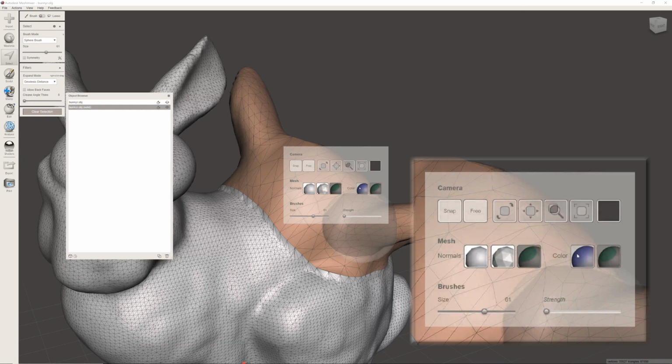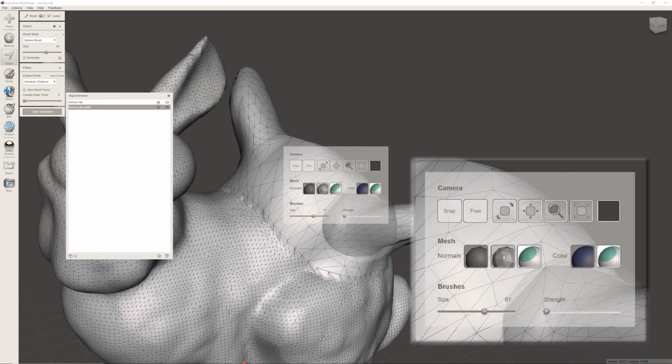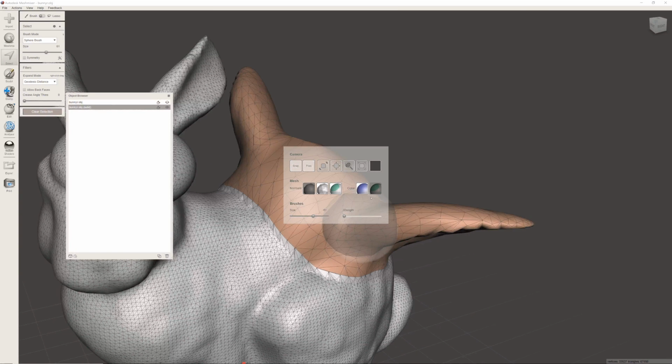Also, you can color your models in Meshmixer, but you will need to be able to see the face groups if you're working on it. So from this menu you can choose whether to see face groups or the color, which for now is only gray because we don't have any color. You have other options for how to see the model. So the wireframe, for example, a more blocky look. We go back to the smooth one and back to the face group mode.